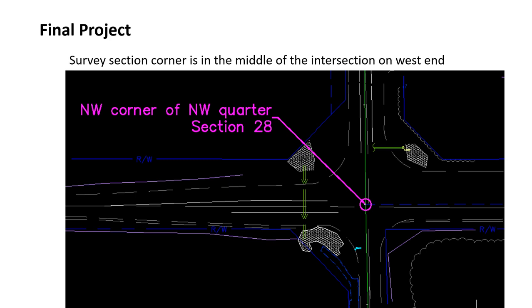There are two different properties. This is where they're going to start, over here on the far left side in the survey base drawing. The first thing you do is download survey base. Then you're going to create a new drawing called whatever your last name is _design. And then you're going to XREF in survey base into your new design file. Everything you draw, all of your contours, all of your annotations, your layout tabs and all that are going to be made inside your new design drawing, which is XREFing survey base. You shouldn't be drawing anything in survey base. Everything you draw should be in design.